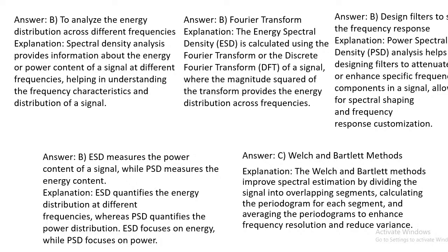ESD measures the power. No, this is wrong. Actually, this is PSD. PSD measures the power content of a signal, while ESD measures the energy content of the signal. So these two will be interchanged. So ESD quantifies the energy distribution at different frequencies, whereas PSD quantifies the power distribution. So ESD focuses on energy, while PSD focuses on power. So this question was wrong. ESD and PSD should be interchanged.